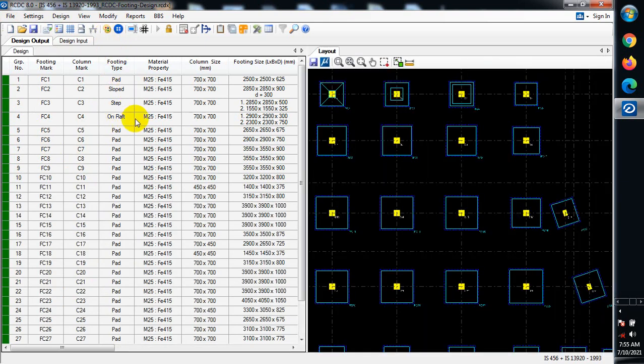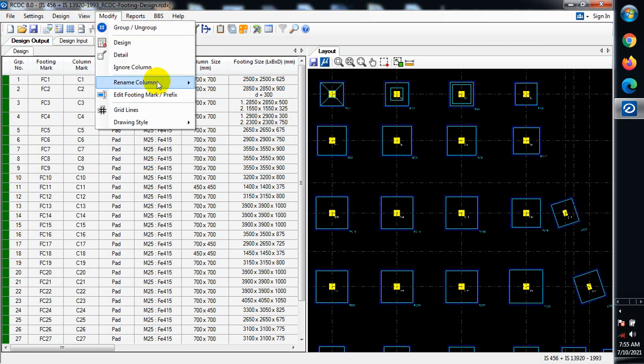Because if you can remember, there are 3 suspended floors, so we have 3 floors up, then 1 ground floor, so it's going to be very, very heavy. So the loadings are heavy, so definitely the size of the base will most likely be as wide as that, and then the size of the column will definitely be large too, because it's carrying a very heavy load.